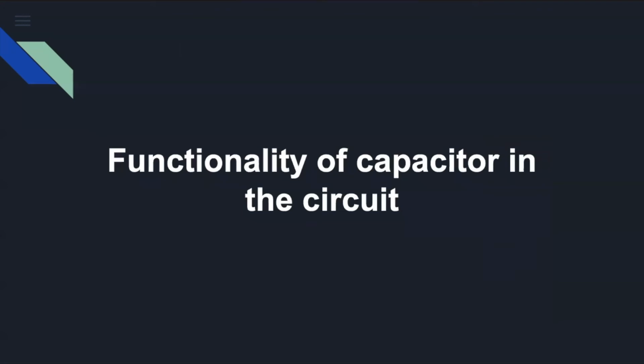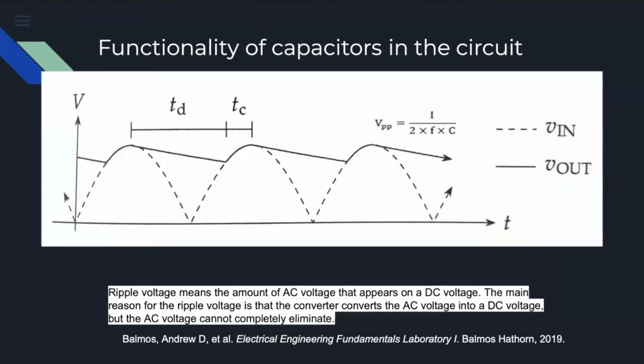Now to talk about the functionality of the capacitor in the circuit. Although the output from an electronic rectifier circuit is technically direct current because all of the current flows in the same direction, it isn't suitable enough for most purposes. Even full wave and bridge rectifiers produce direct current that pulses in rhythm with the 60 Hz AC sine wave that originates with the 120 VAC current that's applied to the transformer. And that pulsing current isn't suitable for most electronic circuits. That's where filtering comes in.